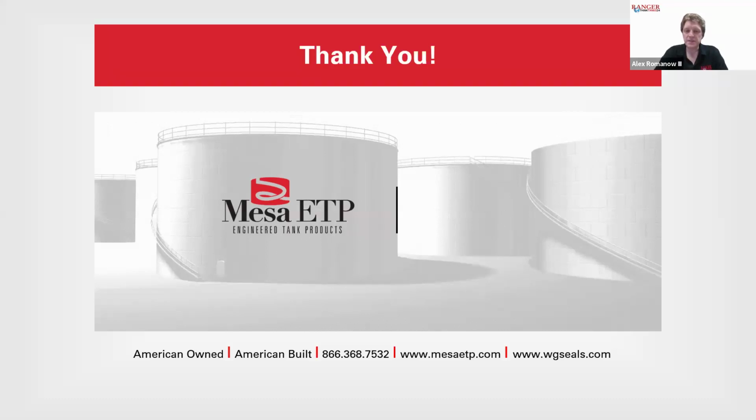There's a couple questions here about, we're getting away from the actual seals themselves, but more over towards the floating roof socks and things like that, and asking about the effectiveness of that. And so, we see a lot of times with a floating roof leg, there's a sock over it, there's a little clamp. Essentially the idea is that we're able to close that off, but it's not necessarily a fully closed system. So when we have a sock like that on, maybe some of the vapor is captured, but really what's the effectiveness of that? At some point that sock is coming off, there's going to be some release. Are we really capturing that much in those? Is it more a method of slowing things down? Is that how we're looking at that?